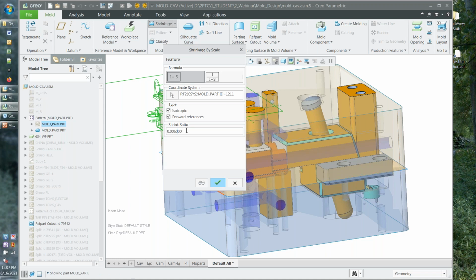It can, of course, be non-isotropic, and you can apply different shrink ratios and different vectors based on a coordinate system. That can be enormously handy in some material conditions and great disparities in component molding, when there are huge disparities of thickness and length and width and other unfortunate circumstances with respect to the core part design that don't necessarily lend themselves to manufacturing well.